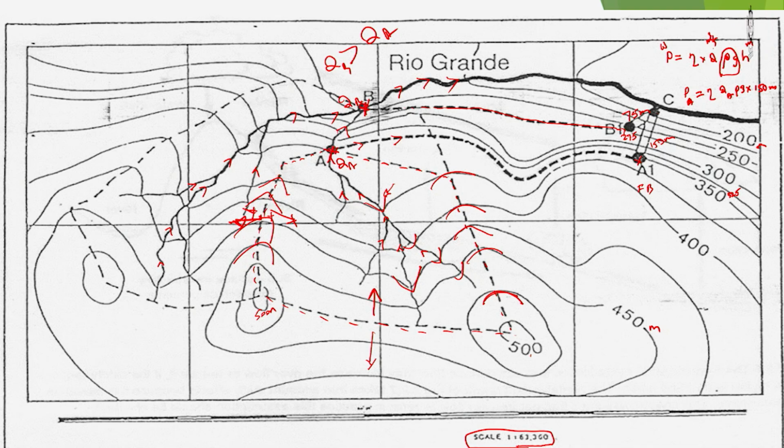So, that goes to this river system, therefore, that cannot be our catchment area, right. So, always argue whether rainwater falling there can come into your catchment area or not. If it cannot come, that part cannot be your catchment area, right. This is initially difficult, but when you are accustomed to it, you can gradually learn how to mark the catchment area.